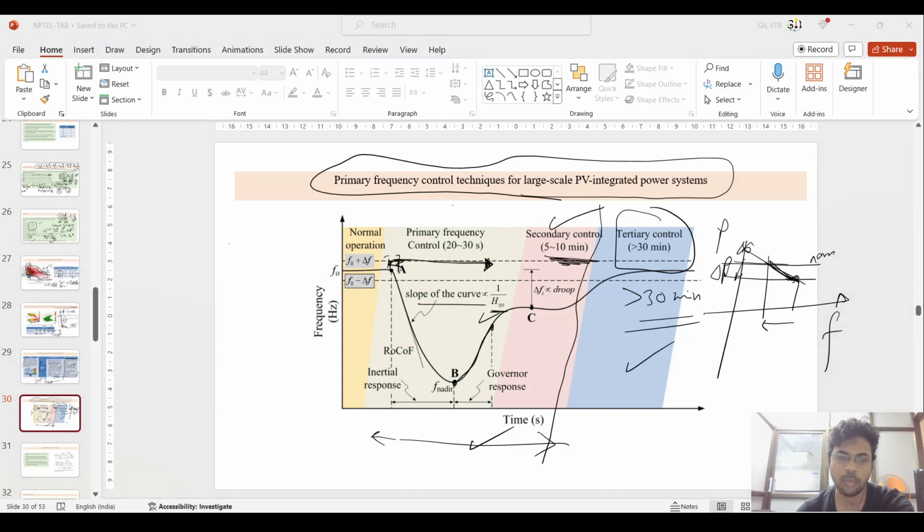The large power demand occurring at that situation makes a reliability issue possible. So what I am saying is that when you have synchronous generators installed in large quantity, the primary frequency response can be provided from them, so that you get the 20-30 second time frame to clear the fault, checking how vulnerable your system is.